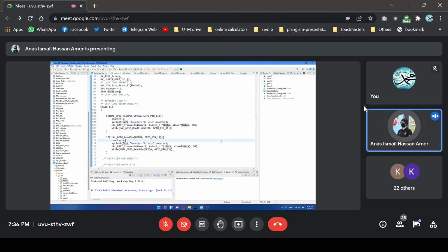It's the same as printf, but instead of printing to the terminal, it prints inside the data argument, which is the first argument. Then we can later transmit. So this is why we're using sprintf. We're also using sizeof here to avoid calculating the size of data, since sizeof is already calculating the size of data. So just use sizeof data.